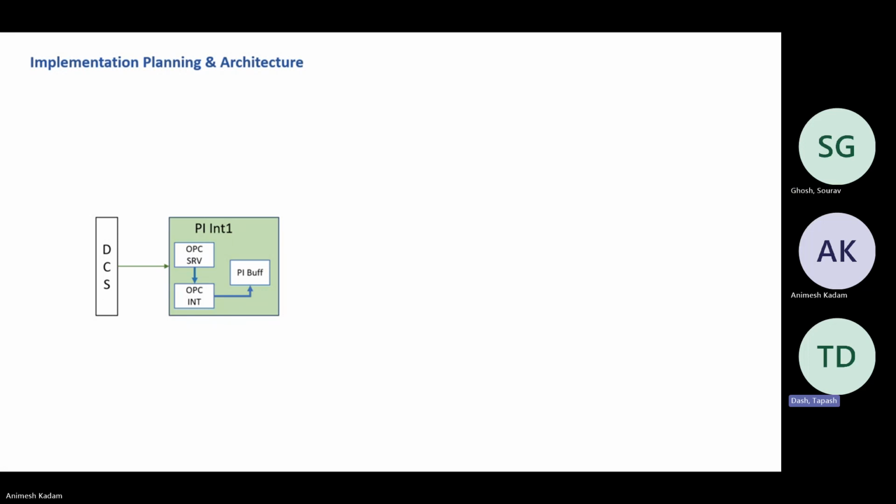I have some knowledge of DCOM settings. Whenever we do PLC to server or SCADA to SCADA communication, at that time we need to do some DCOM setting, but I don't have much idea on that. Yeah, no, it is just a basic DCOM setting. You need to make sure that in OPC Enum on both sides you allow that particular user which is running the interface, so it has access on the OPC server and the interface node also, the admin access or the access to the data.